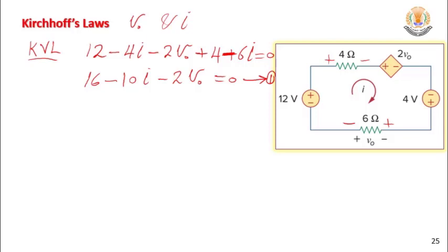Equation 2, from where? As long as you have a dependent source, each dependent source will create another equation. If you look at the dependent source, how can we call it? It's a voltage source controlled by what? Controlled by what? This means the equation written on the top of the source. Quickly, how can I call it? Voltage controlled voltage source. Clear?